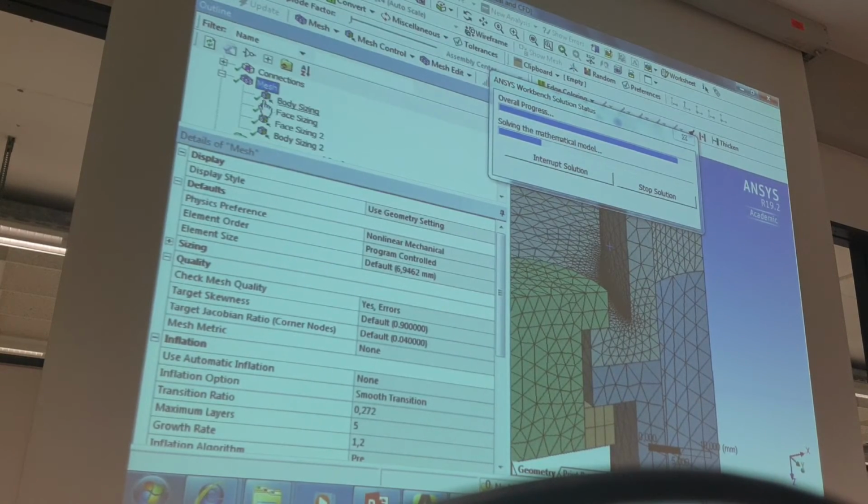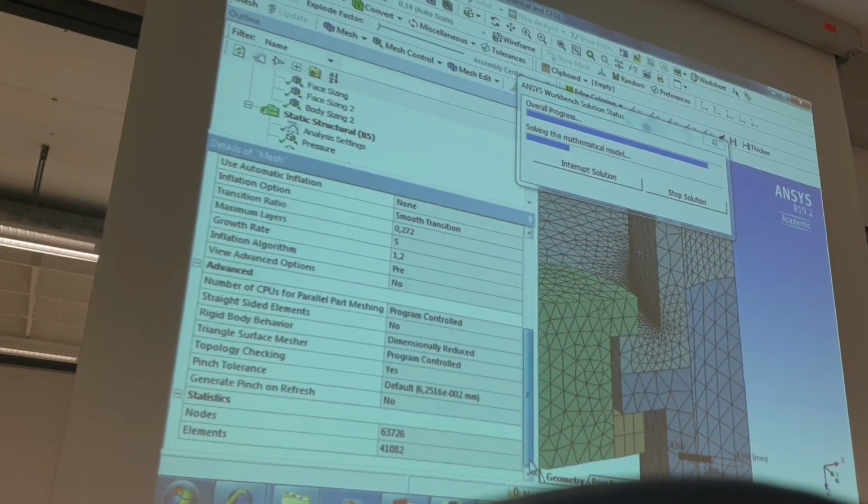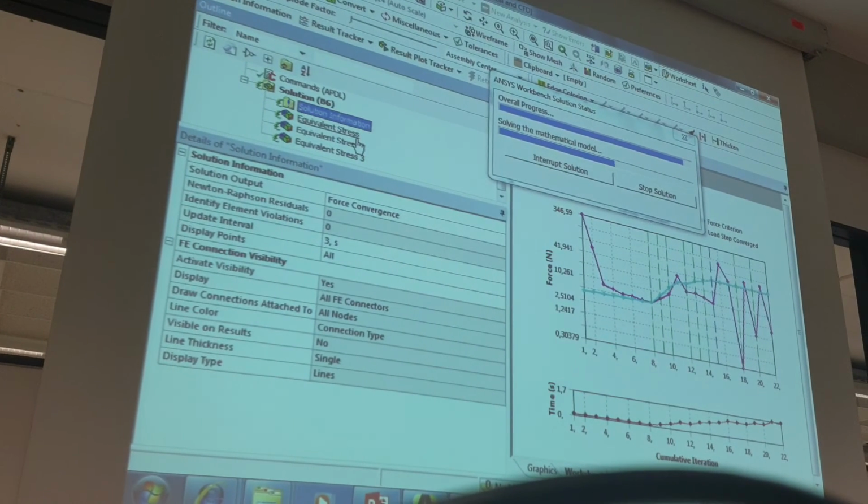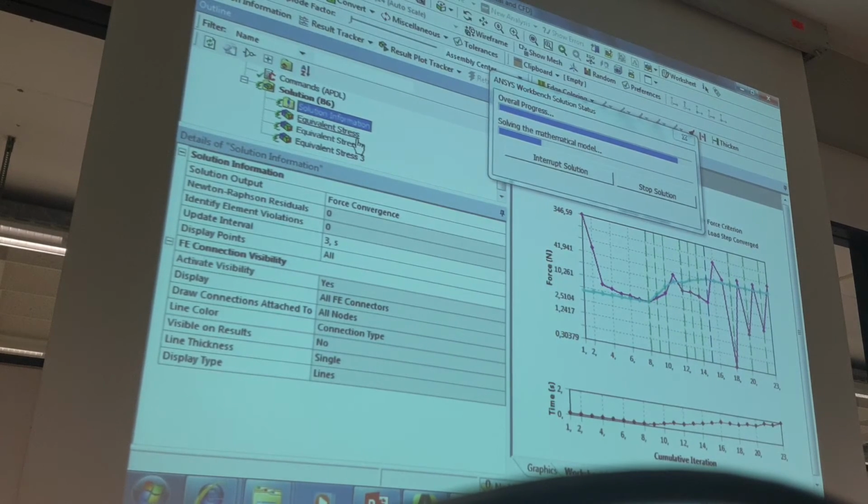Okay, it means only how we can use our theory to be quick. So 60,000 nodes. Okay, and we see now results, and how much time we need. And then we change the last thing. Yes, we say that we want to calculate only linear, only quadratic, only one part where we need. Yes, this radius we want to calculate quadratic, and the other parts we can say linear. Okay, now it's finished.